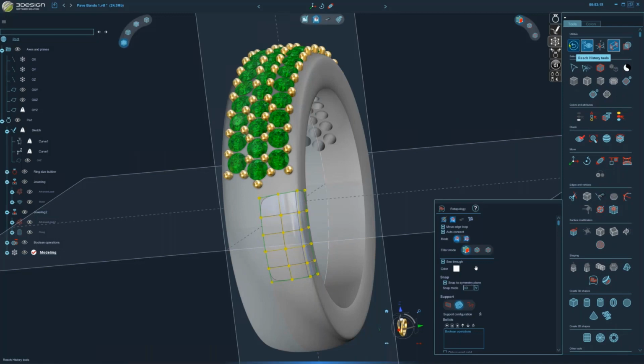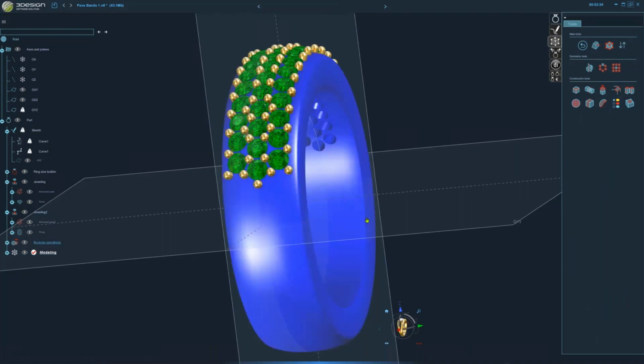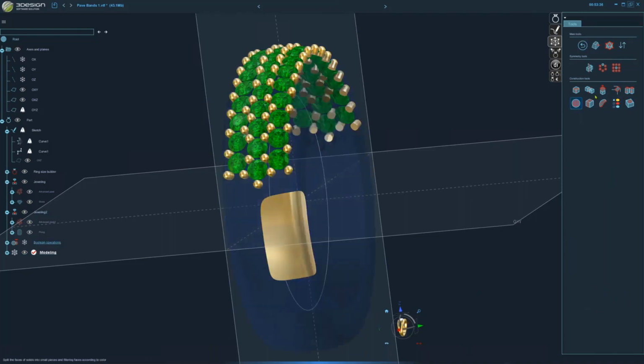We can just hit exit, just like you exit a sketch or any other of your modules to get back to 3DESIGN, you hit the exit button. Now, when you do that in 3Shaper, we're not going back to 3DESIGN quite yet. We have this history tools, this parametric tools submenu in between. And this is where you're going to add your mirror. Let me freeze my ring so I can see my surface there again. We're going to do a mirror.